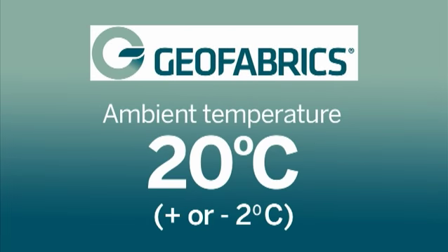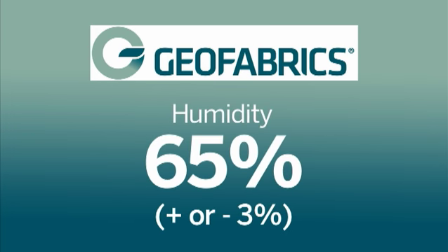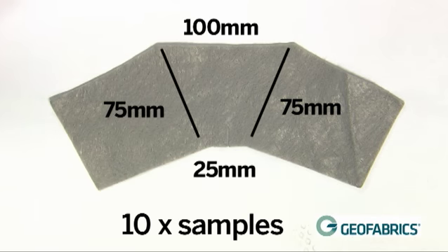The standard environment for this test method is an ambient temperature of 20 degrees Celsius, plus or minus 2 degrees Celsius, and humidity of 65%, plus or minus 3%. 10 trapezoidal specimens per sample direction are required.